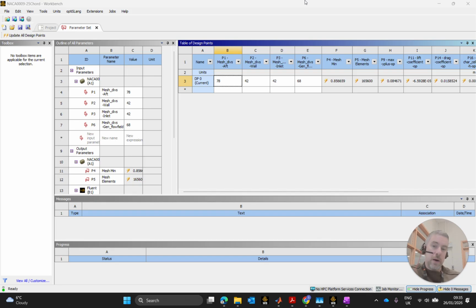So we could find that for a particular airfoil at a particular Reynolds number, it behaves very well numerically at a certain grid refinement, but it behaves terribly from a physics model standpoint. It's not indicative of the physics for the given turbulence model we have chosen, for the given discretization scheme we have chosen. So it doesn't necessarily reflect that our physics are bad or good.